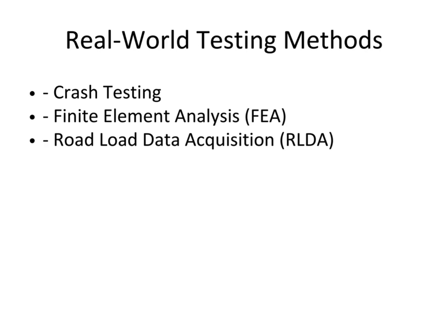Lastly, we have road load data acquisition. Data acquisition is basically a method of measuring different loads and stresses on a vehicle while being driven in the real world, like putting sensors on a vehicle and driving it on bumpy roads, plain smooth roads, dirt areas or different types of conditions, and acquiring that data and using it. So this is called road load data acquisition.